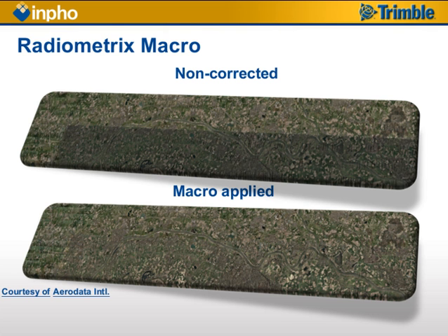What you see right here, on the top side there is this data set where you clearly see there is a couple of images which are much darker than the others. So that's probably coming from 2 different flight dates, and just selecting some 10 images, recording the macro to enhance those images a little bit, and applying that macro to the rest of the data is providing then already somehow a homogeneous result, and AutoVista can then do the fine work to enhance all the little differences between the photos.